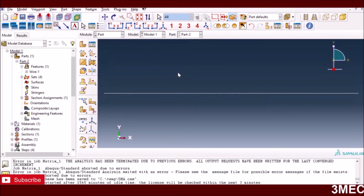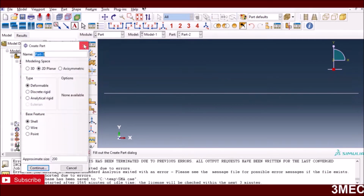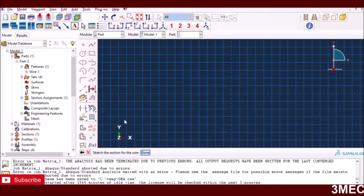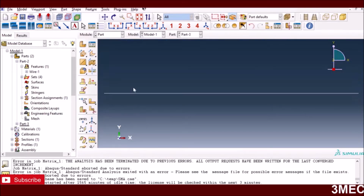Okay, let's jump into the details of how to model this. I have already created a model. What I did to model the fiber was create this single line. How you can do it is go to the create part option, select 2D deformable, and then wire. Then you can select a cable. In that case I think it was 6 millimeters long, so I'm just modeling that, and you see this is the length of that fiber. I'm calling it cable, sorry, but it's fiber.